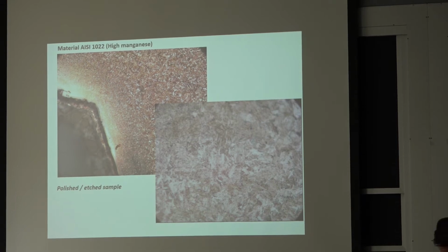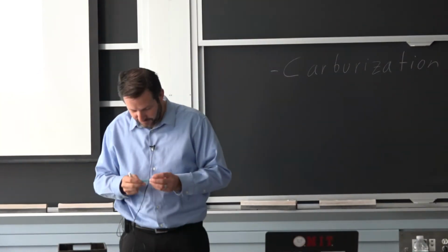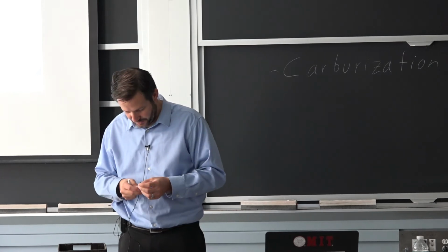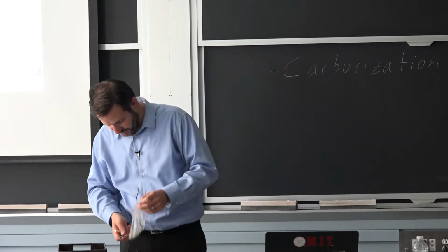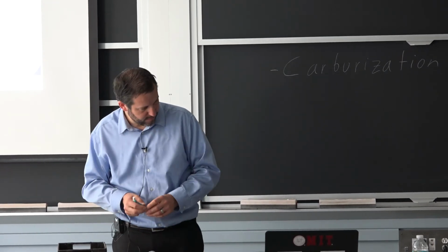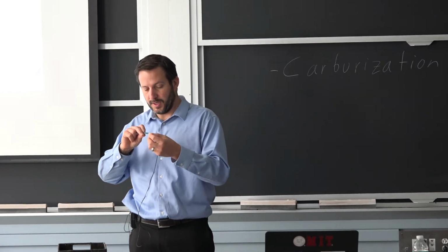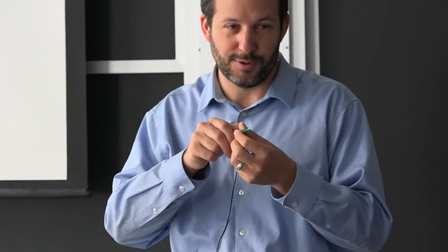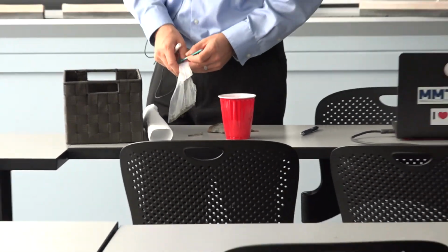The pieces I have here, and we're not talking about things that are super sophisticated, are just these kinds of fasteners that can be used on buildings. Not this one. I didn't bring the self-drilling one. There are some fasteners that have a little bit of a drill bit at the end, and then a threaded portion. So you drill the hole, and then you're able to put the bolt in right after the fact. So it saves a lot of installation time.